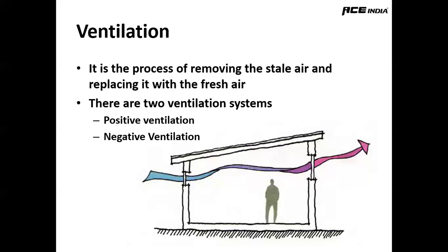Okay, fine. Once again, negative ventilation is typically removing the stale air with the help of a fan. Here, there is no admission of fresh air directly. We will be forcefully exiting the existing air from the area with the help of fans. So what will happen? Those areas will become low pressure. In order to balance out, the atmospheric air will automatically infiltrate into those areas. So that is negative ventilation.